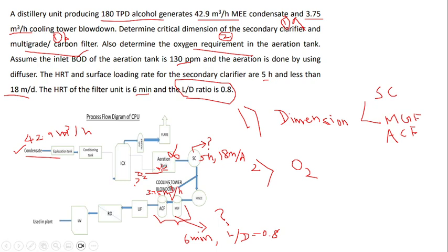It is the term that mentions the two streams: one stream is named condensate, and another stream is named cooling tower blow down. We are not calculating the water blow down. The data is given directly: the flow rate of these two streams. That was a little confusing, that's why I asked. No problem.